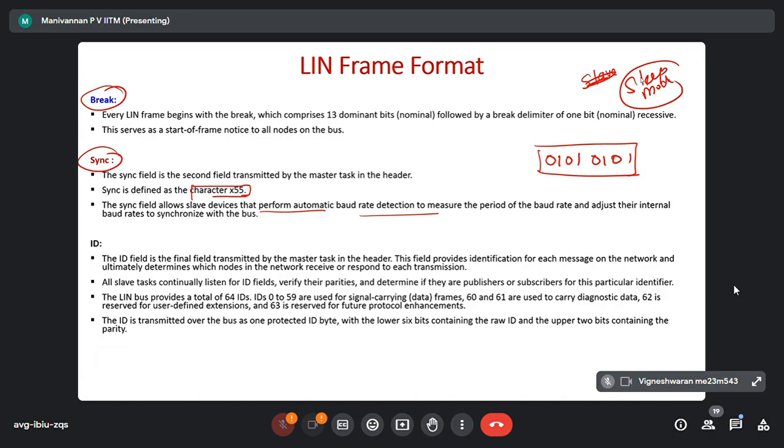That's why, if there is no activity after some time, including CAN control, all the ECUs go to sleep mode so that your battery is saved. Right? So they may be asleep also. Correct? To make it awake, I'm just giving an example, when the master wants to send, the vehicle is already working, but there is no call. So to see that the device is ready, like calling hello, we would do that.